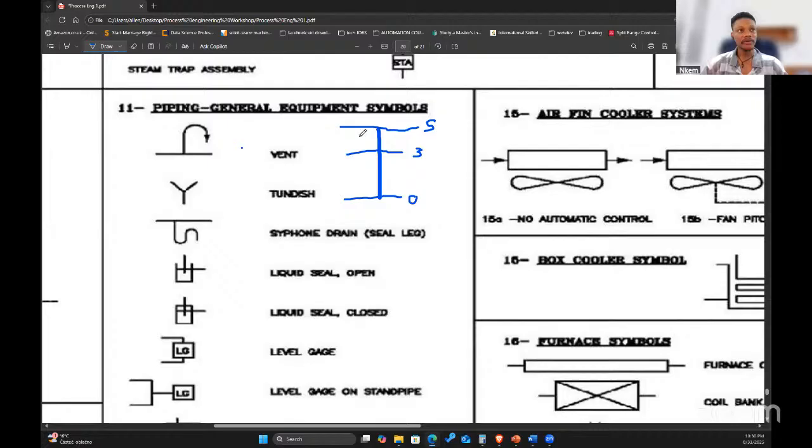Now they have what you call your safeguarding system, your safeguarding window. This is to protect the system from explosion, accident, and whatever. So this is probably going to be around 4 bar. These are based on the standards, on the API standards. These standards will guide you on how to design this equipment, the vessels and the pipelines. So on the line, you have your relief system. On your relief system, you have vents.